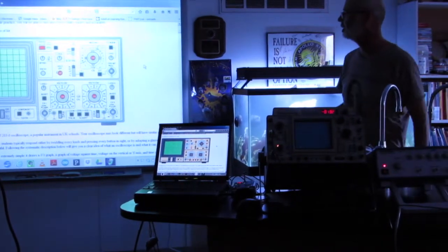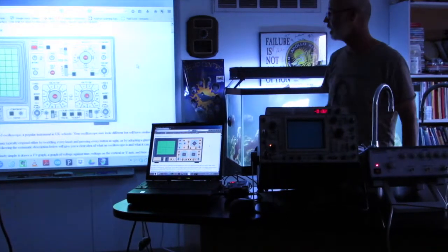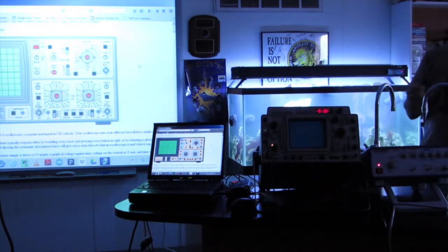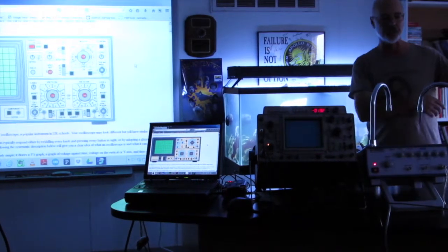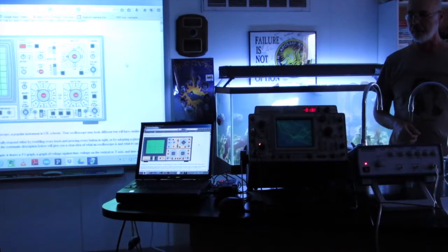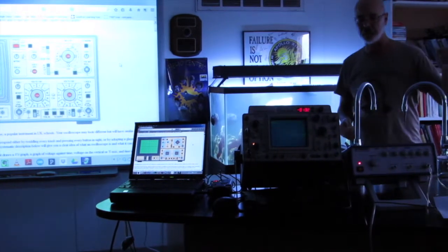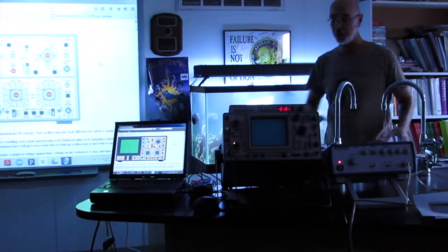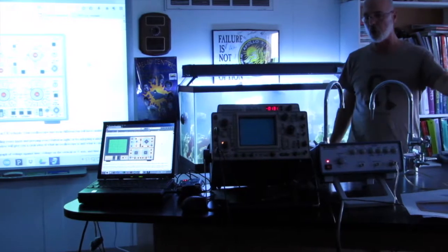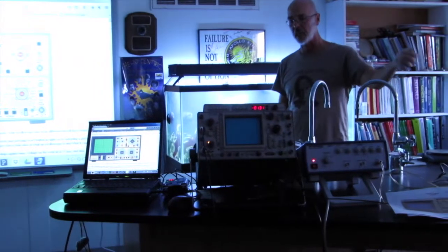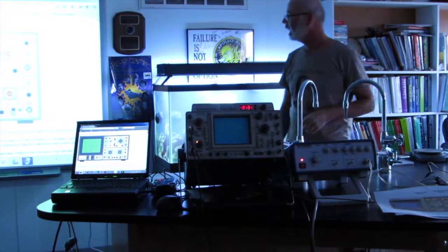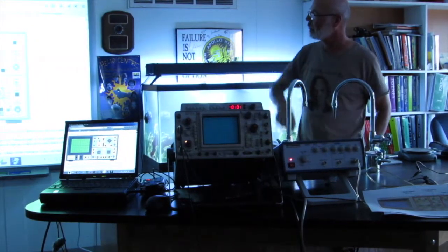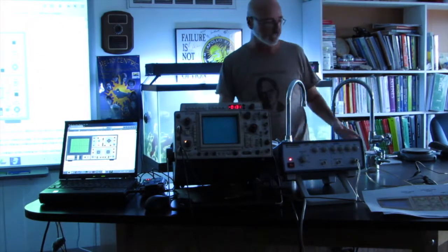That's good if you're troubleshooting TV sets which operate off of line frequency. You can also do an external trigger, where you can take an additional probe and probe something in the real world that may start a sequence of events. Let's say you know that a pulse going into a circuit will trigger a series of events, and you want to watch that series of events. You can probe that voltage that's going to start the sequence, run it into your external trigger, and then when that pulse comes into the trigger, it'll trigger your sweep, and then your sequence of events can be seen.